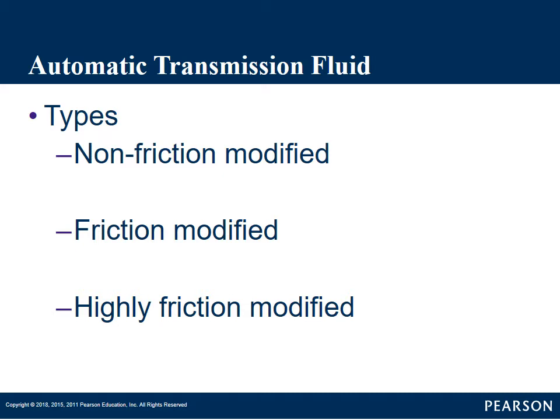Well, when you apply pressure to a piston in a clutch pack, it squeezes that clutch pack and tightens it up, and then that clutch pack's attached one way or another to a gear element of our planetary gears, and it holds that gear. What happens is for comfort, they take different steps into allowing those clutches to gradually engage with each other.